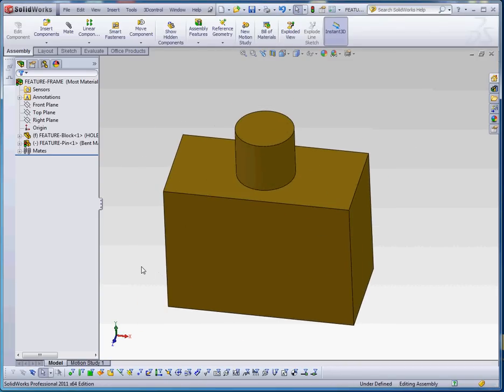So in this video I'd like to show you a little bit more about geometric dimension and tolerancing, and what happens when we have a dimension that defines maybe the diameter of a pin that goes into a cylindrical hole, and what happens when that diametrical dimension is true all the way throughout a non-cylindrical item like this. We need something extra that helps define this a little bit better, and that's what geometric dimension and tolerancing tries to do with feature control frames, and we'll talk about that here in just a minute.